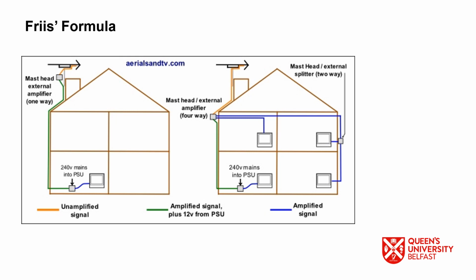Our next topic is Friis formula. We also call it Friis transmission formula. We have seen in previous slides that if we have a single receiver, then it will definitely have an input noise, and the output noise will be the total output noise, which will carry the noise that is created by this receiver plus the amplified noise, that is this one. So here we will get a combination of both of them.